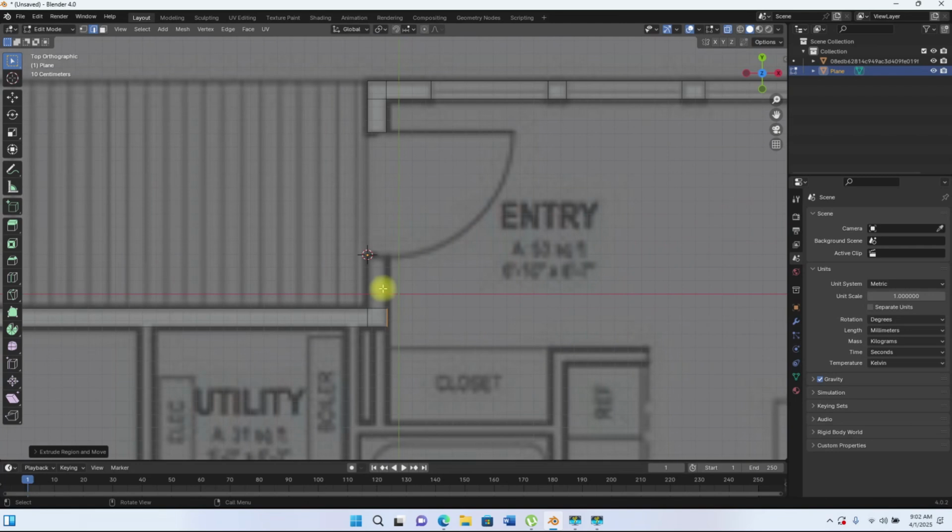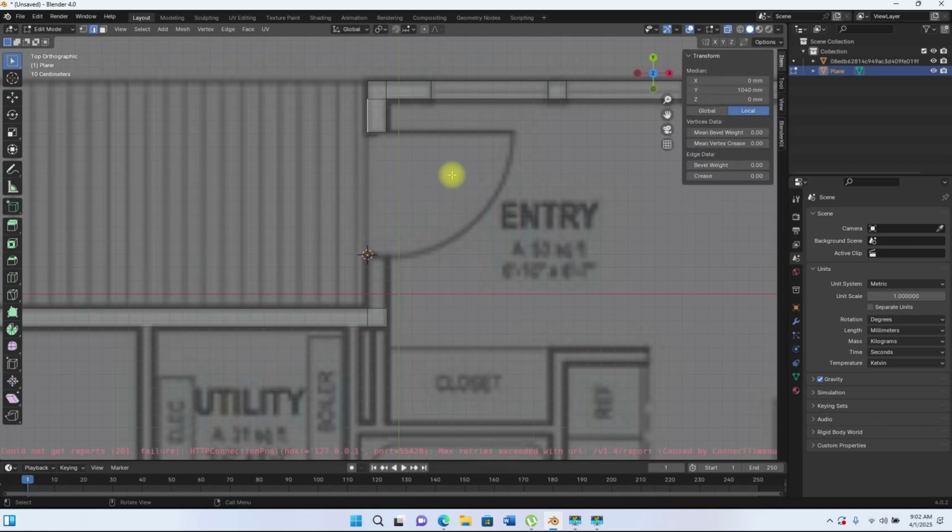So at this point, I quickly want to go off the time lapse so I can explain here for you. If you notice this edge here, and I hit my N key, you notice that along the x-axis, it has a value. The value is 0. If I select this, you notice that this value is not totally 0. So I need to make sure that they are on the same level along x. So I'll just make this 0. So it's going to shift that.